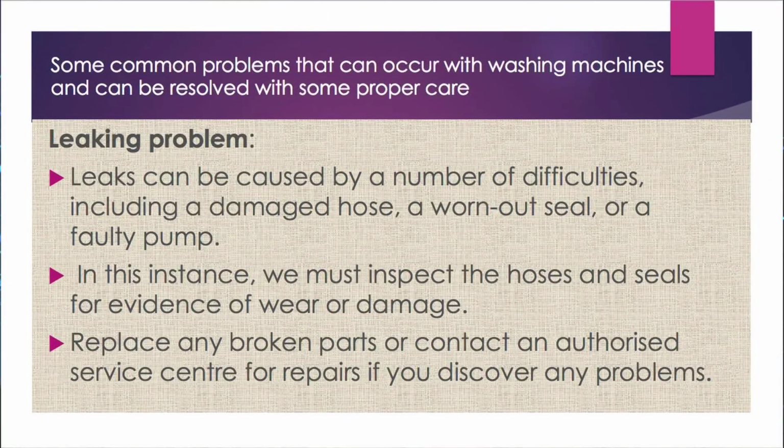Another important problem that is seen many times is the leakage problem. Leakage can be caused by a number of difficulties, including a damaged hose, a worn out seal, or a faulty pump. In this instance, we must inspect the hoses and seals for evidence of wear or damage. If there is damage, then replace any broken part or contact an authorized service center for repair.